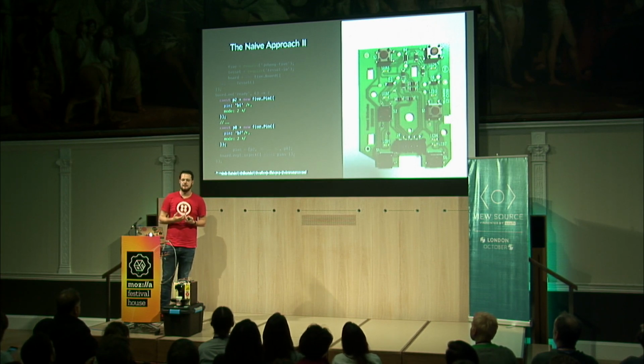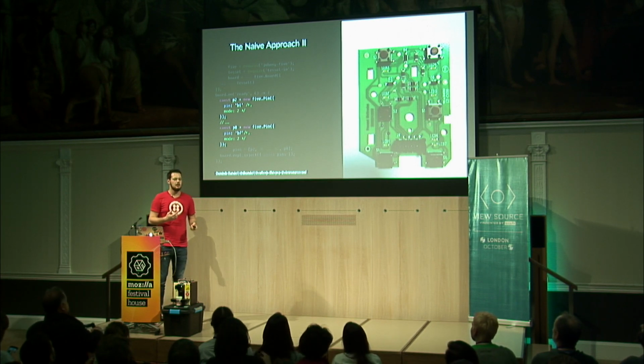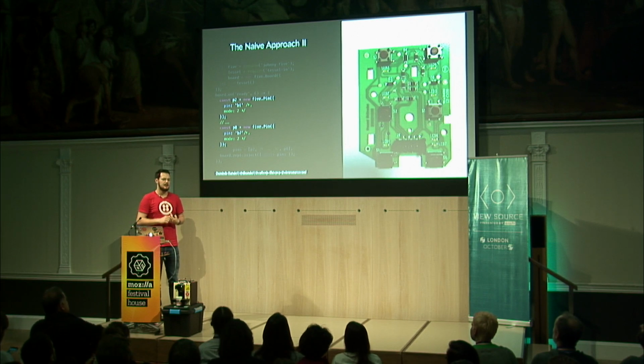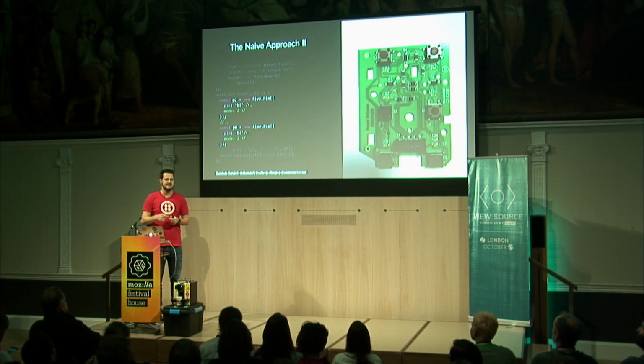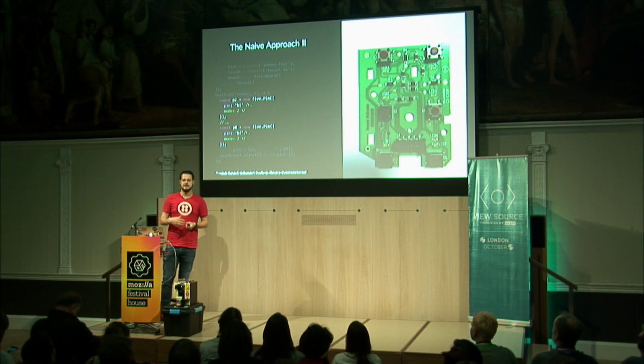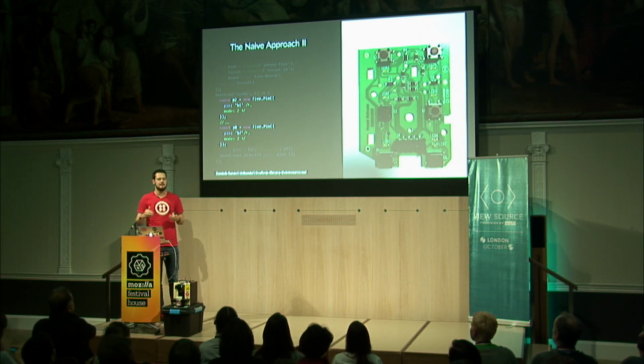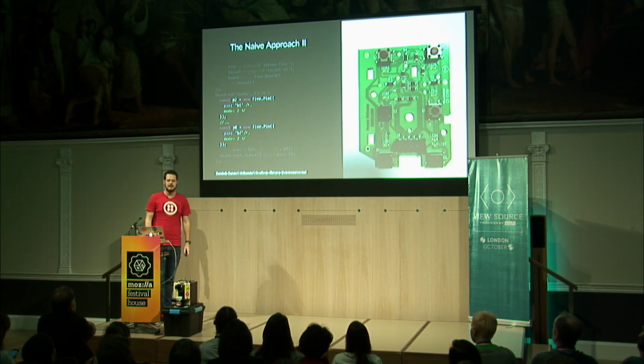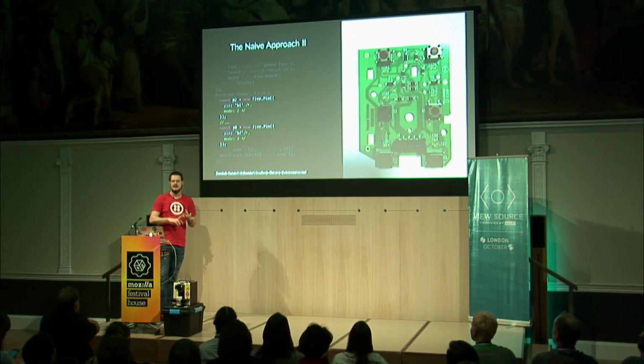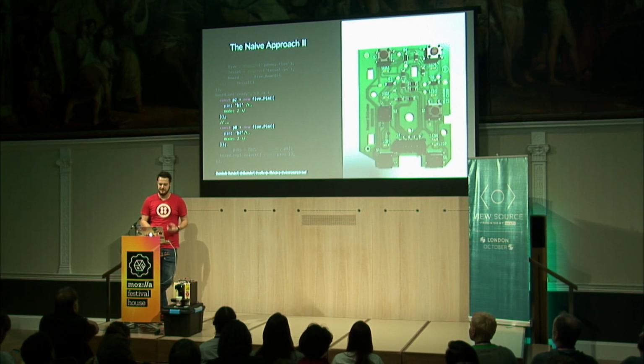And this helped us because suddenly we were able to better manipulate these values by setting them on purpose to high or low voltage, and similarly we were able to read better values, which was just high or low. Based on that, we could figure out that of pins 2 to 8, pins 2, 3, 7, and 8, those 4, were actually reacting to button presses in some manner.